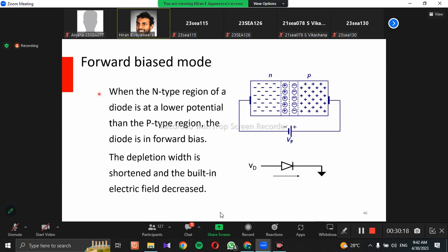Right. Then we'll consider the other situation, the forward bias situation. Now the battery is connected in a different way. By default, the electric field is from positive to negative. I will label the electric field because of the material EA, just to make it clear. And now the electric field from the battery is from positive to negative. This is the positive terminal and this is the negative terminal of the battery. That electric field is coming in this direction, E battery. Now, what's the resultant electric field? It's EB minus EA towards this direction.